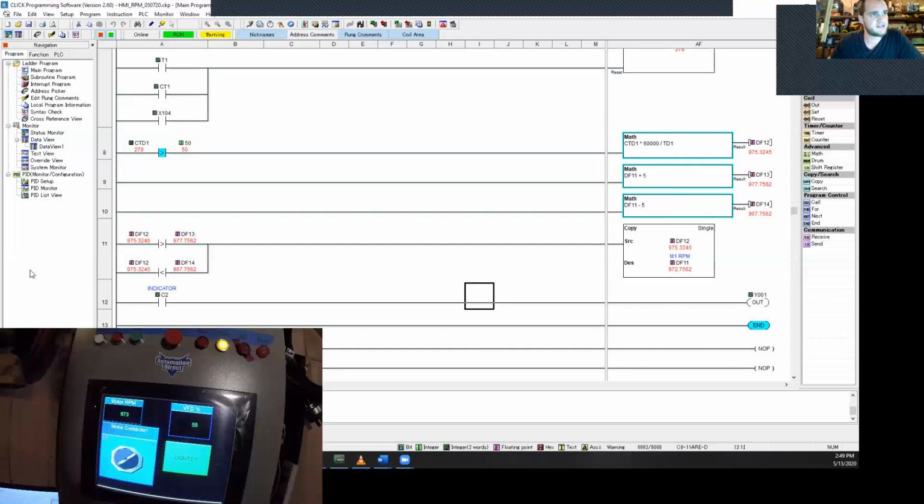So what I did here is, at the expense of 2 points in memory, I took the currently calculated RPM and I add and subtract 5 and write that value into 2 different blocks of code. And then on the next line, I do a Boolean comparison of the current value against those calculated values.